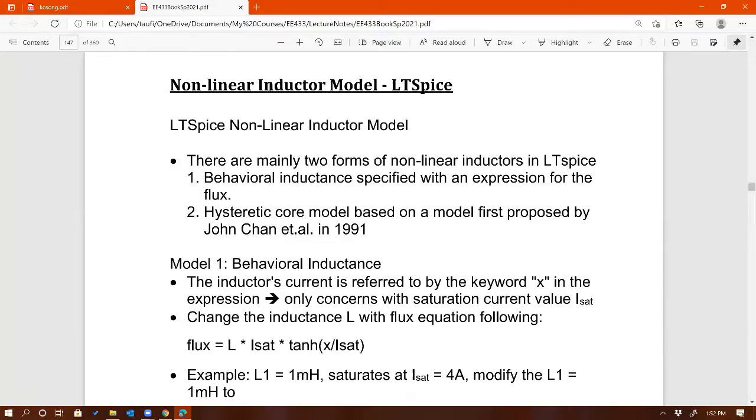So you would first make sure that the overall DC to DC converter works, with all these linear models of the components. Once the DC to DC converter works, then you start looking into the different components and change the model of each component into a more realistic, real world type of model.